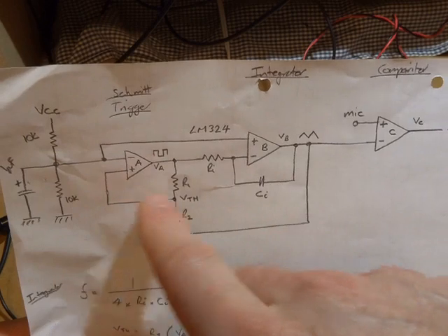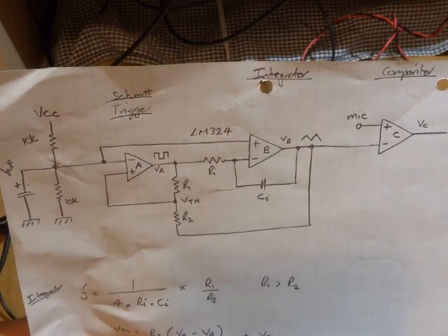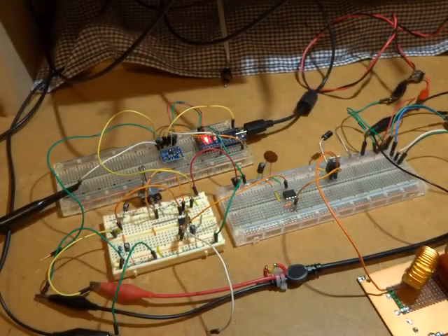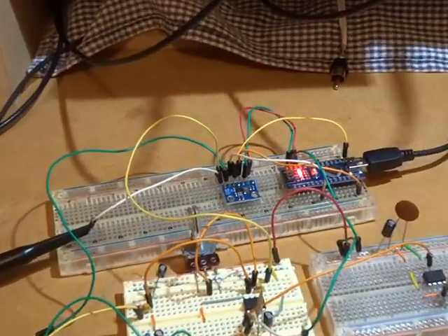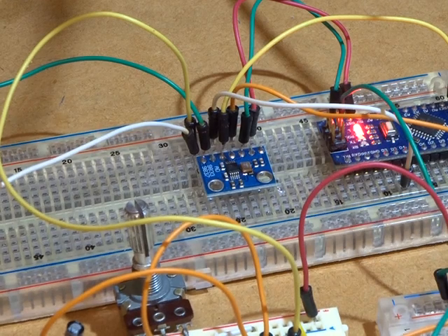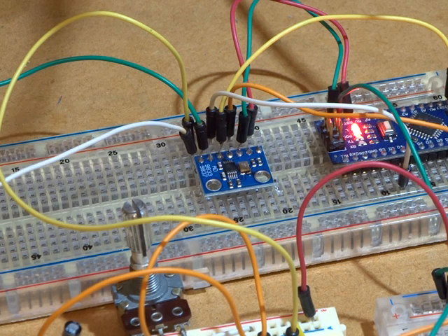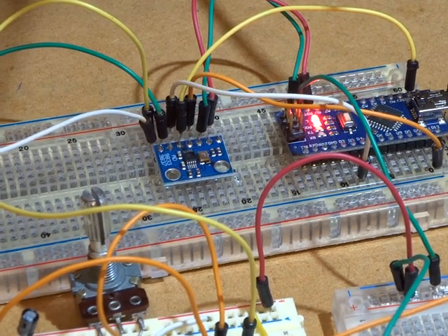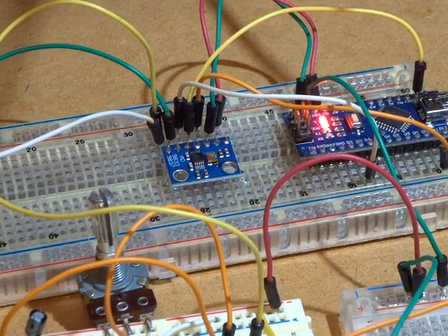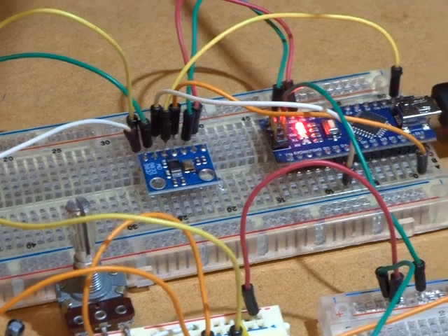So in the end, I elected to try a little chip that I haven't used before, an AD9833, and that's what we see over the back. It's just a couple of dollars here in New Zealand. It's quite a common device. It can produce triangular, sine wave and square waves, with a very simple communications protocol with a microcontroller. I'm using a little Arduino Nano to drive it.